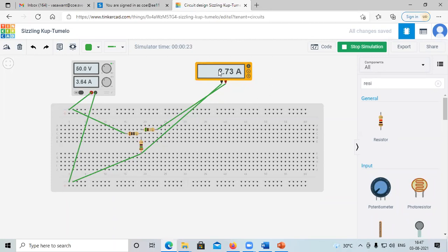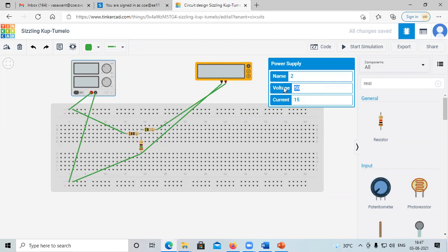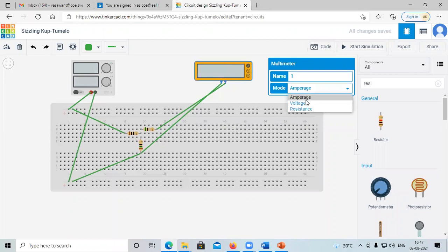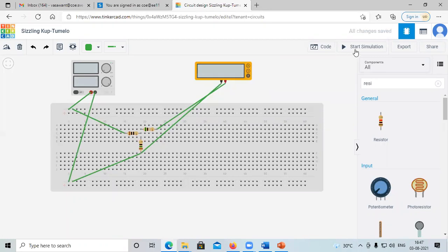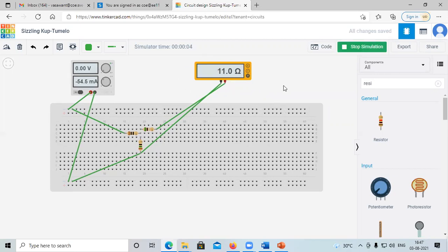Okay. So IN, that is short circuited current आहे. IN is verified by using this simulation software, that is Tinkercad. Tinkercad वरून आपण IN calculate केला. Now similarly, procedure for RTH किंवा RN साठी same procedure. Voltage source should be short circuited, it is nothing but 0 value, and we measure the resistance. Again start simulation. Value of resistor is nothing but 11 ohm. Okay, त्याची value 11 ohm.